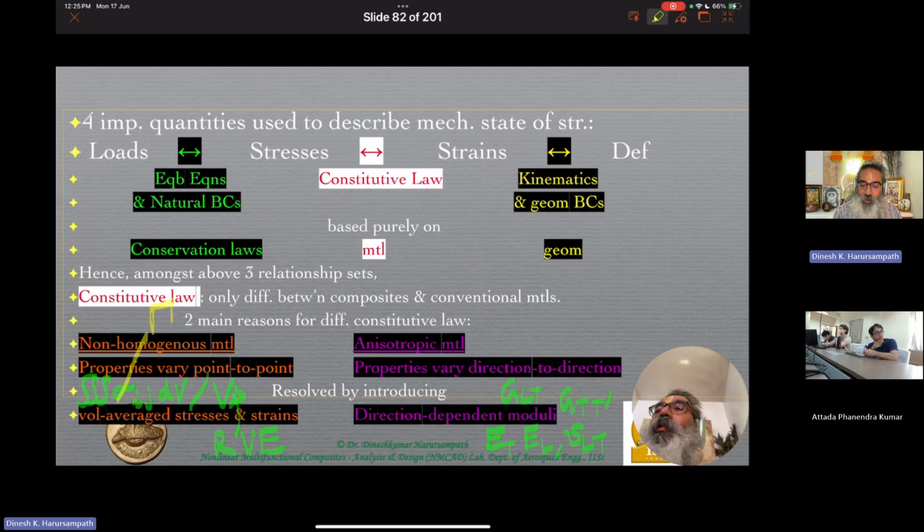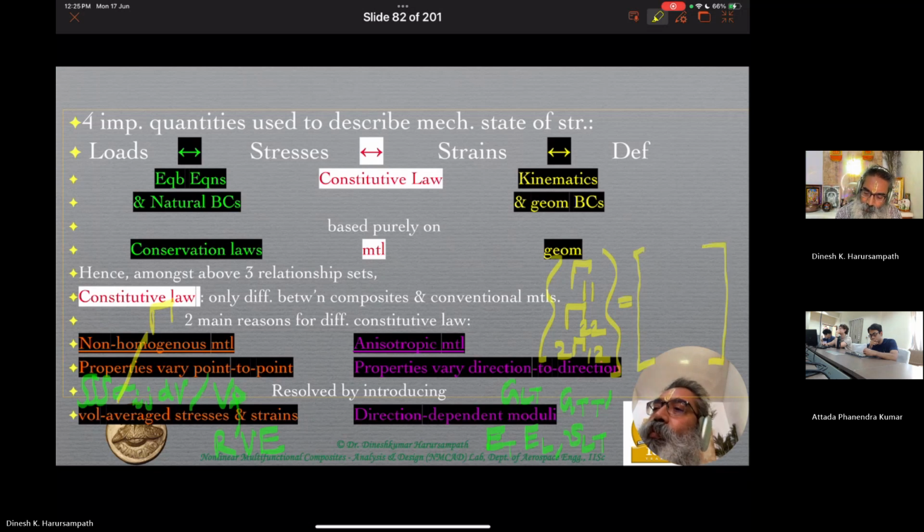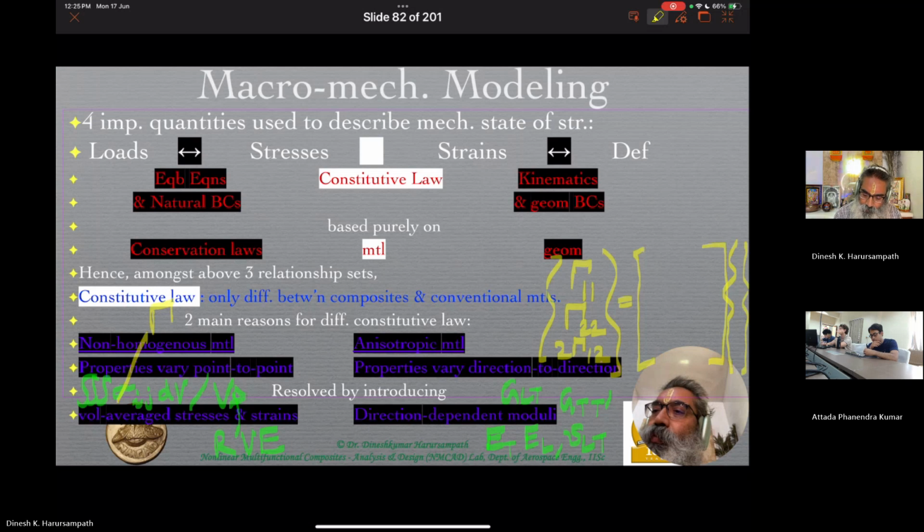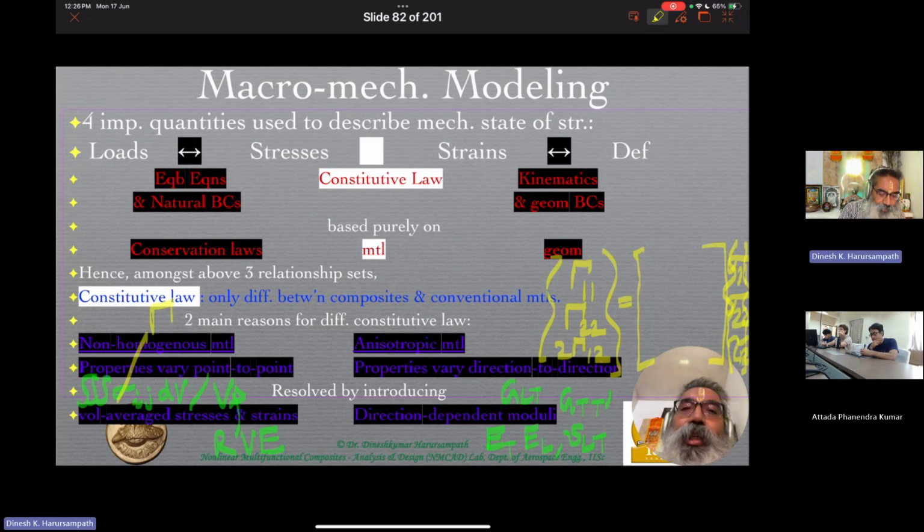And the final form of that constitutive law, whatever we introduced, remember, is a 2D constitutive law because of the plane stress approximation, where we just said that we are relating our, let's say, gamma 1 1, gamma 2 2, and 2 gamma 1 2 in the principal material directions, which means that we are talking about 1 as L, the longitudinal direction, and 2 as the transverse direction, or direction perpendicular to the fiber.